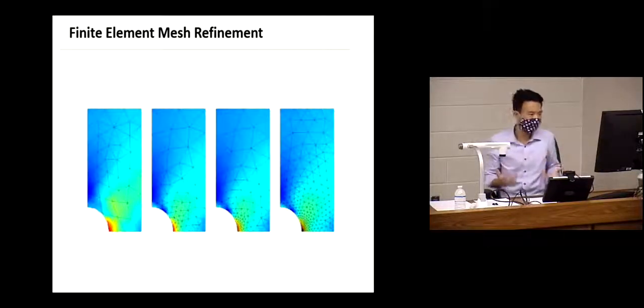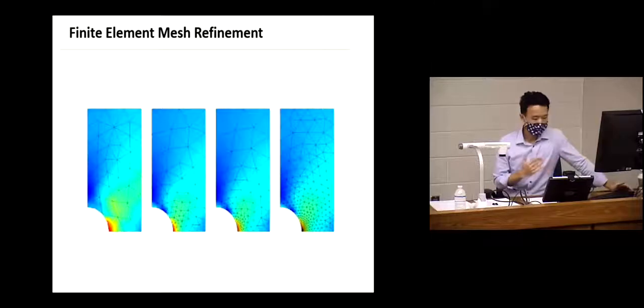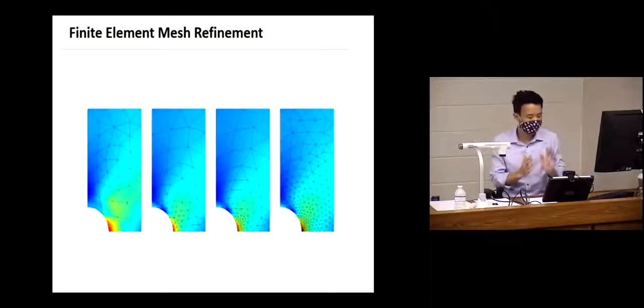This is what a finite element practitioner routinely does to balance the computational requirement with accuracy. I brought this up because the student version of Abaqus is limited to 1,000 elements. Okay, so it's free, but there is a limitation. You can't really solve real problems with 1,000 elements. It's too small. But for learning purposes, by adjusting, that still works, right?